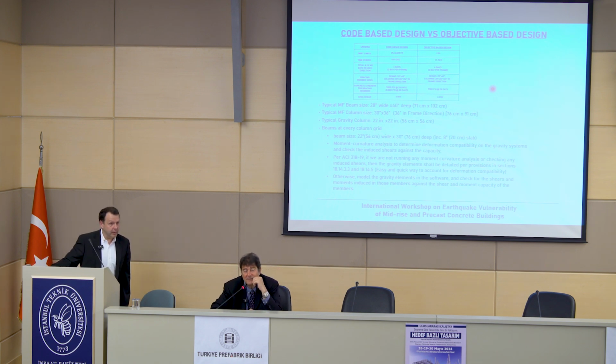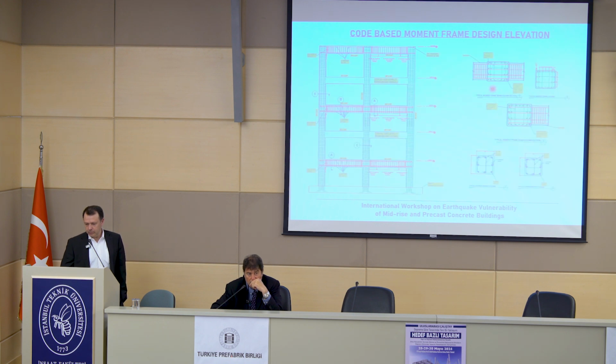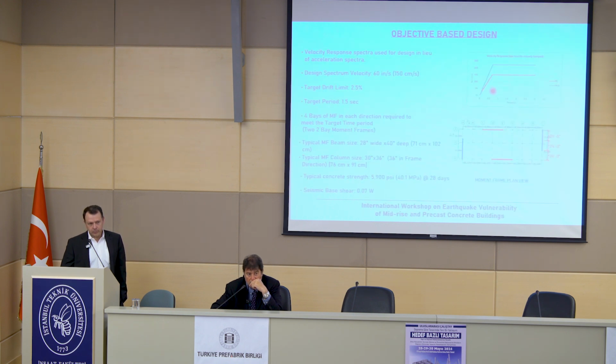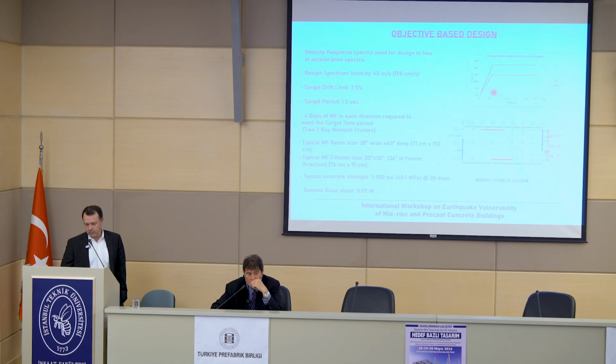You have to involve two lateral load resisting systems in the moment frame plane, but the distance is nearly 64 meters. In Turkey, for shear walls we use a maximum of 40 meters for diaphragm action. How do you handle that for the lateral moment system when you place them at the ends, in the case of earthquake loads?